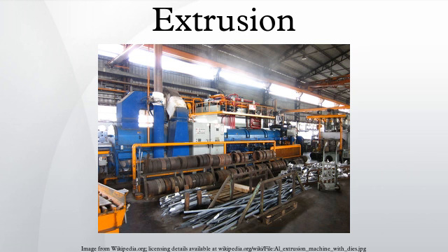Direct extrusion. Direct extrusion, also known as forward extrusion, is the most common extrusion process. It works by placing the billet in a heavy-walled container. The billet is pushed through the die by a ram or screw. There is a reusable dummy block between the ram and the billet to keep them separated. The major disadvantage of this process is that the force required to extrude the billet is greater than that needed in the indirect extrusion process because of the frictional forces introduced by the need for the billet to travel the entire length of the container.